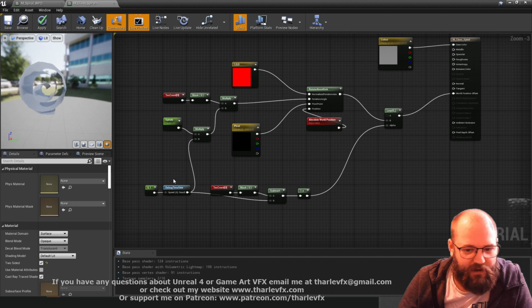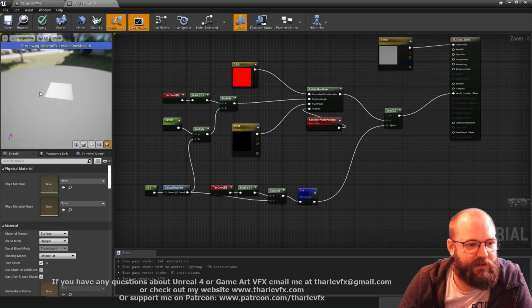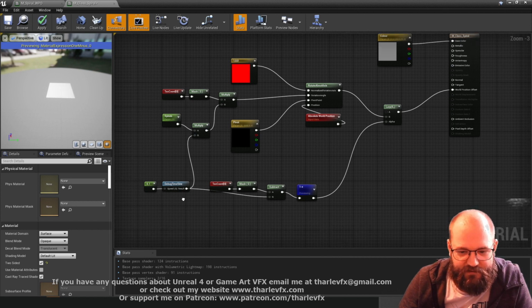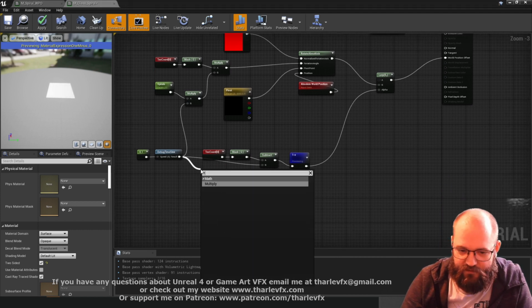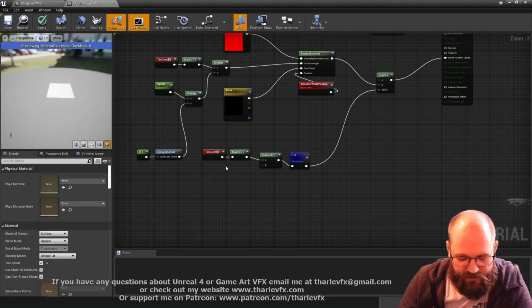well, one problem we've got here, if I just preview this node, we should be getting white, and then our black mask should come up. Let's maybe go a little bit slower. Well, the amount we want is to go from pure white to pure black, so we're not subtracting enough. So if we double that, in fact, rather than doing that, let's use a lerp.